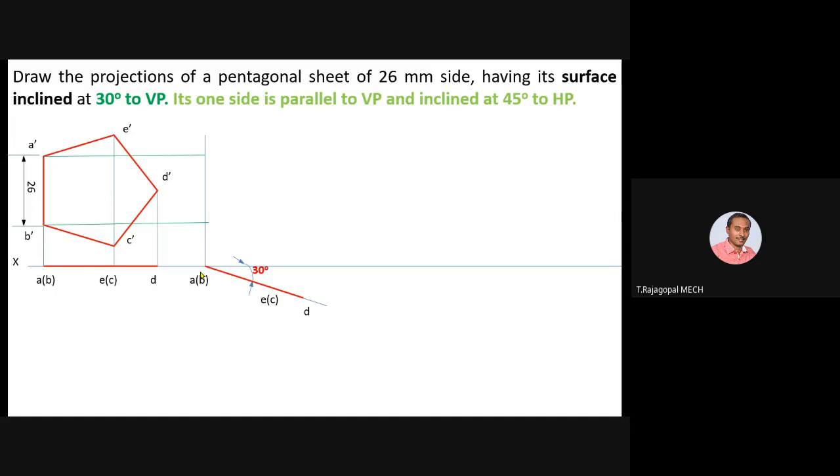See, correspondingly you can select the points. A, here it is, AB is the projector from top view. It is meeting at one point. This is B1 dash. And if you go above that, this A dash and A from the top view is meeting at this point. You can fix it as A1 dash. So A1 dash, B1 dash is fixed now.